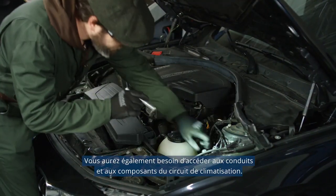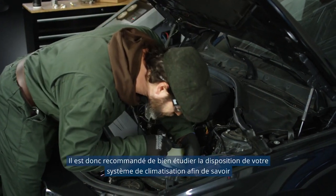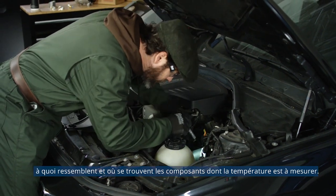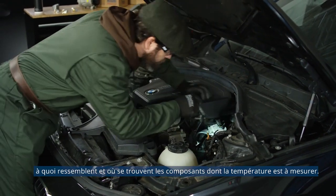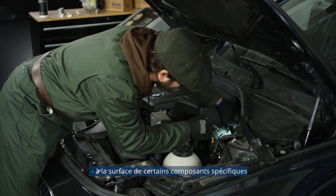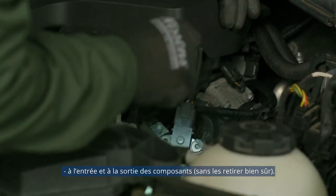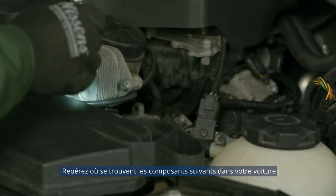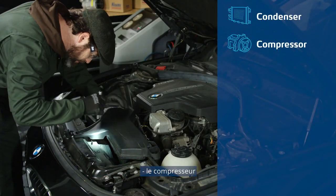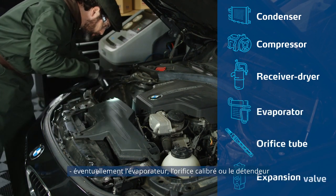You also need easy access to the AC loop ducts and components. Some of these can be hard to access, so it's recommended to learn your AC system's layout beforehand to get familiar with the design and the placement of the most crucial components to measure. There are several places where temperature should be measured: on the specific component surfaces, on the component's lines, or at the component's inlets and outlets, without detaching, of course. Find out where in your car the following components are located: the condenser, the compressor, receiver dryer, and possibly evaporator, orifice tube, and expansion valve.